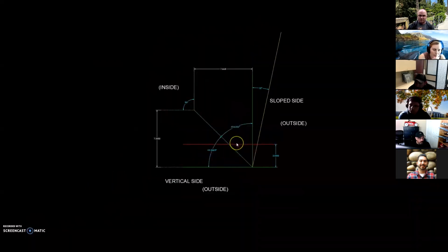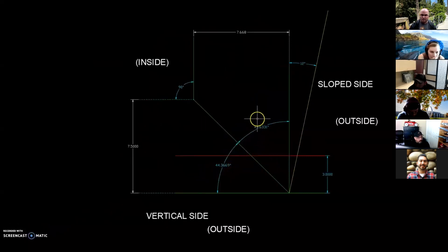With these three projection lines in place, and knowing that any footprint of the corner along the slope will always be the same, but the location of this will change, moving right as this goes up along the slope. While we are still looking at this image, let me say the next step will be copying the bottom footprint. Moving this toward the right, using the intersection of the face of the slope side with the red horizontal line as the base point.